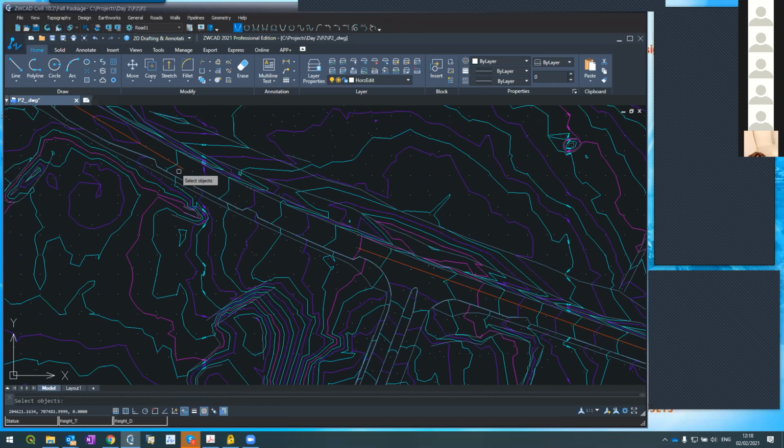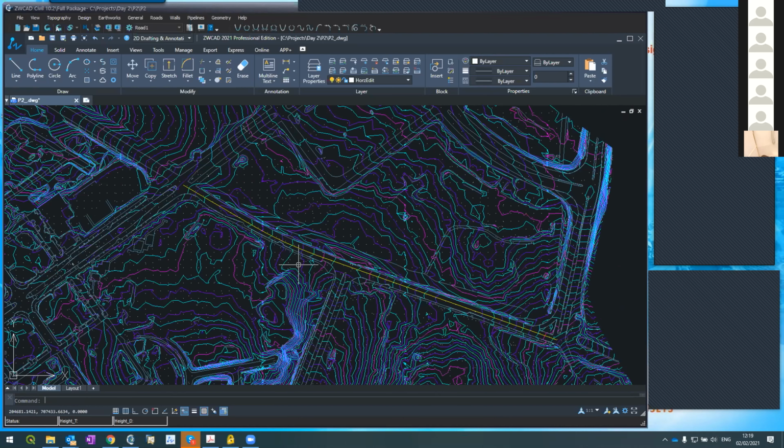It's called line length fit arc, fit curve. So line, he asked me, do you have a transition curve from here to here? I say 0. And everything, I just press enter because I don't know the radius. I just put a clothoid 0 and the system will automatically use a default radius. Since I enter 0 transition, there's only one solution, and this is the curve that the system creates for me between these two lines.